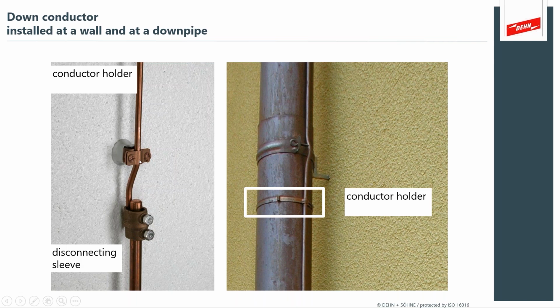That was a real key aspect in the standard that we talked about earlier, that the IEC methods really want you to focus on test and maintenance. As much as we want to install a system and turn around and walk away from it, the lightning protection system is there for fire protection. And so you don't want to ignore it. So every year, for instance, your fire extinguishers are inspected. Why wouldn't you put the same emphasis on something else that's going to save your life in your building? So there's a lot of emphasis on these types of connections.